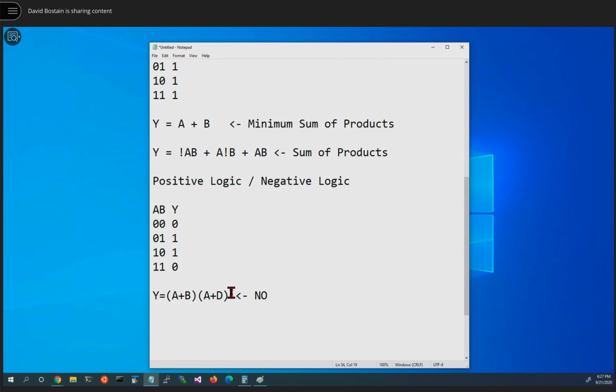We want everything to be a sum of products, which are things that look like this, where we do the products first, and then we sum them up, which is basically to say the ands happen before the ors. You'll notice here also I'm using an exclamation point to indicate negate this variable. It's not A. When I write this out, or if I have a better font, I'll actually put an overbar over the A. I won't put an exclamation always in front of it. It'll have a line over the top, and that means not as well. So you'll see both notations.